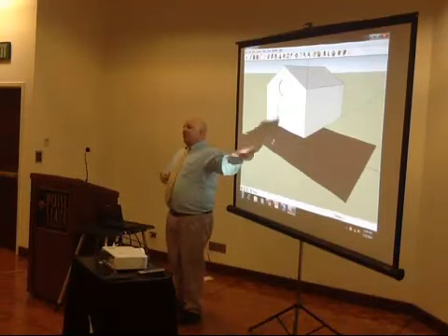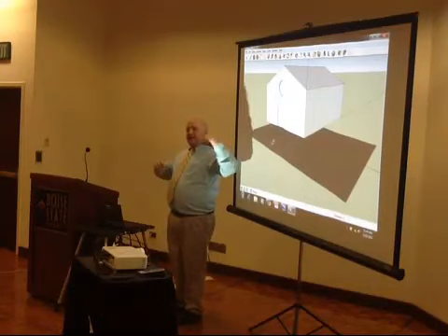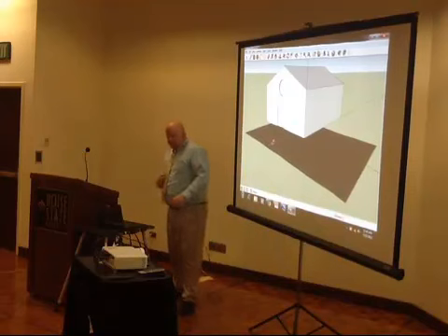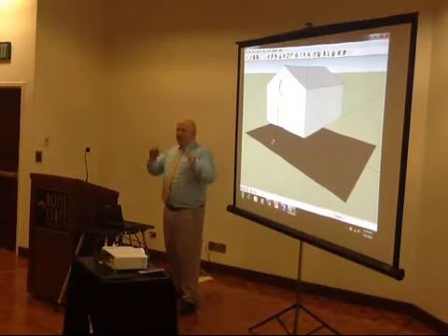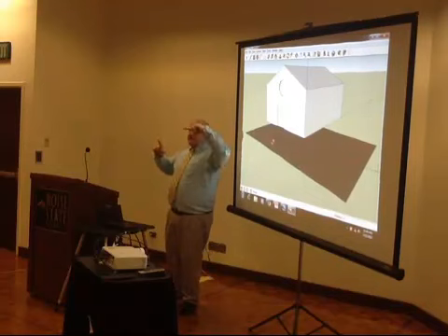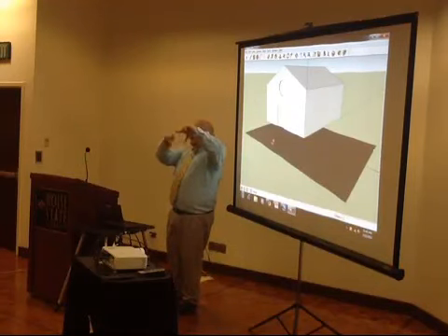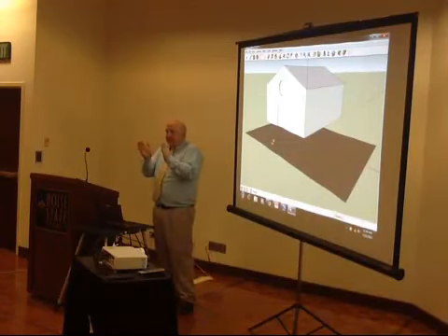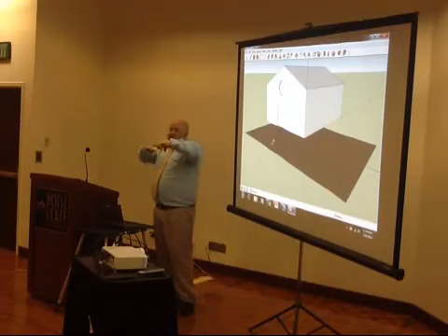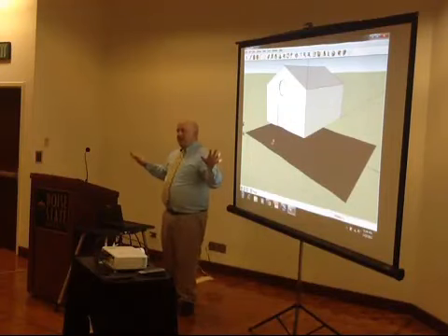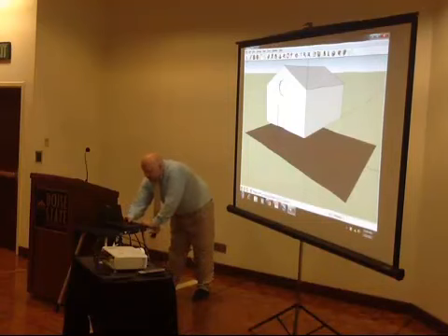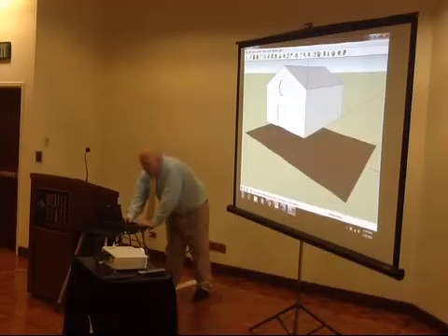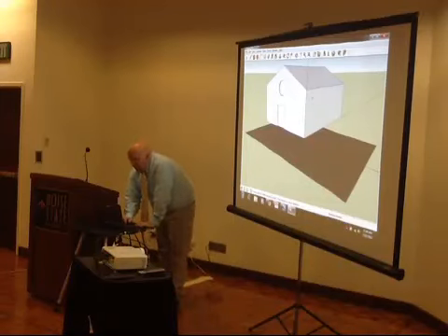the advantage would be, the reason you want to do it is because, well, the reason you start with that process if you're going to be modeling a building is because you actually use the picture to define the original parameters of your building. When you're drawing that rectangle out, you can drag it right over the top of the image that you've snapped from Google Maps. That not only makes sure your size is correct, but you're then positioning that object in GPS space. So this is where I was referring earlier to the fact that that's what we want to do first when we're doing models.